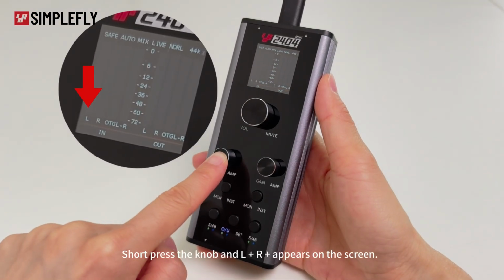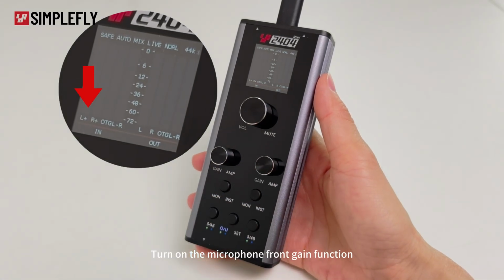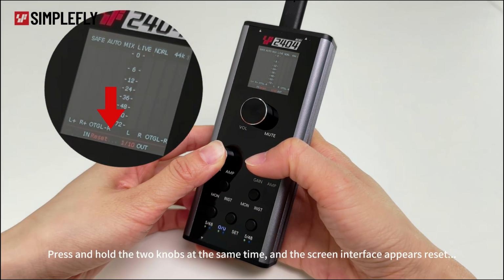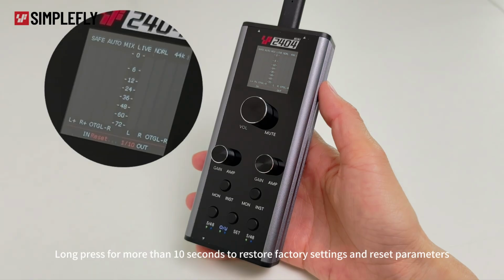Short press the knob and L+R+ appears on the screen, turning on the microphone front gain function. Press and hold the two knobs at the same time, and the screen interface shows reset. Long press for more than 10 seconds to restore factory settings and reset parameters.